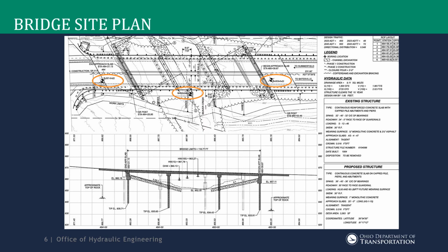I want to point out, circled on the top, the soil borings for this project. If you don't have soil borings, you can't do a scour calculation, and you also need the hydraulic analysis as well. You want to familiarize yourself with each boring and where it is, because you want to take the soil properties from a specific boring location depending on what you're looking at.